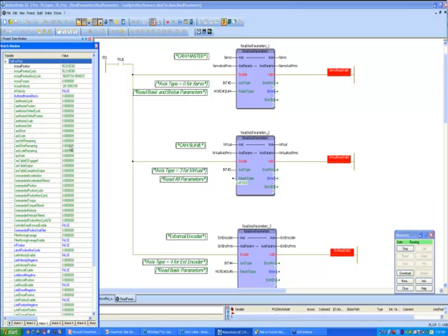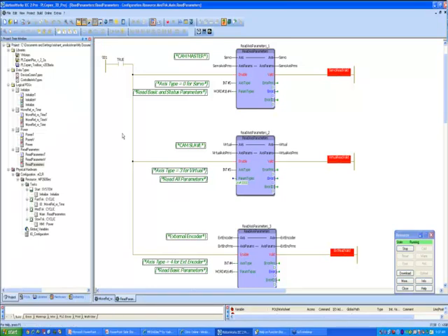It is important to note that if all parameters need not be read at all times, you should never, remember never, place this read axis parameter block in a very high priority, fast task, because internal to this block, it is really reading all parameters at all times. So it is important to pick and choose or wisely decide which task this particular block should go into.